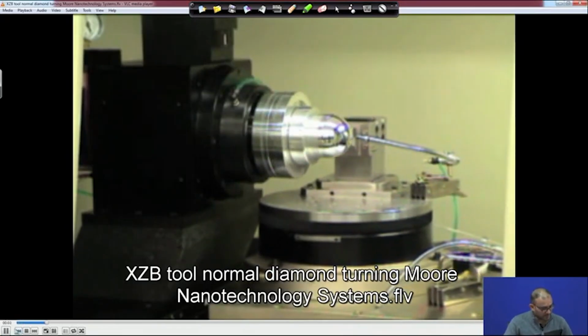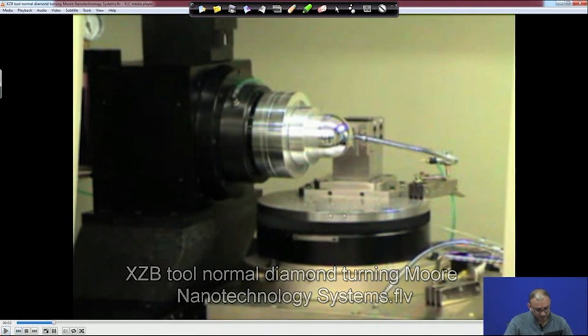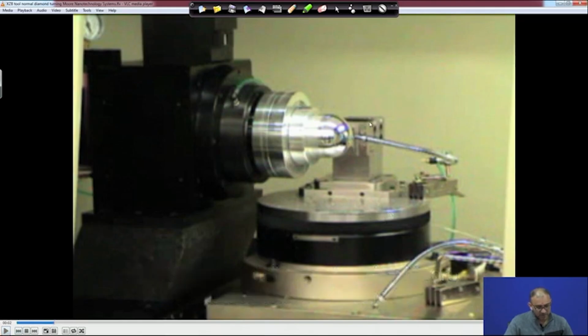So, this is the r theta mode. Now, you can see this is the same rotary table here, your tool is located here, your workpiece is here, and your tool is actually moving around the surface. So, you can create some type of spherical shape here. Depending on the radius of rotation of this particular cutting tool, you can get the same surface on a workpiece.